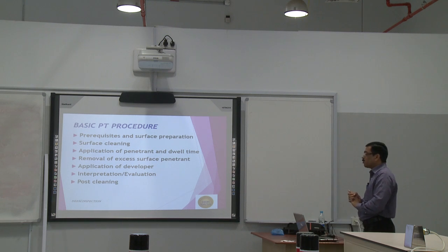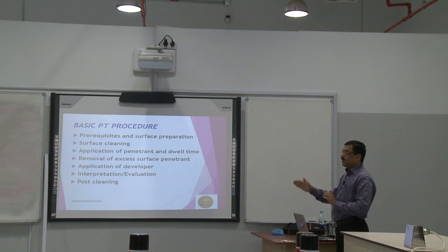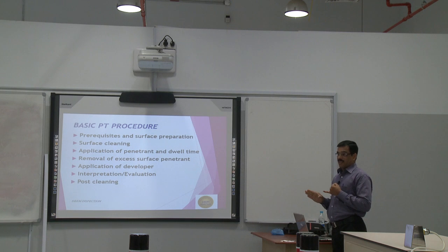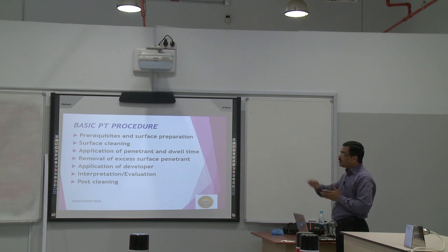So we are doing interpretation and evaluation, and finally we will do post cleaning, because in penetrant testing it is very important to do final cleaning, because this material will go for further processing. It already has chemicals on it, and the interaction with some other chemicals may damage our material, with future corrosion or something. So last, post cleaning. So these are the simple steps we have to do.